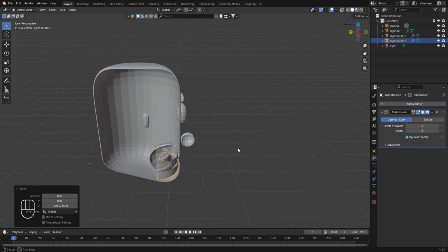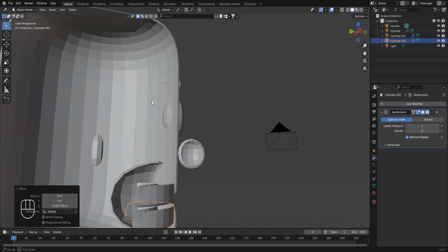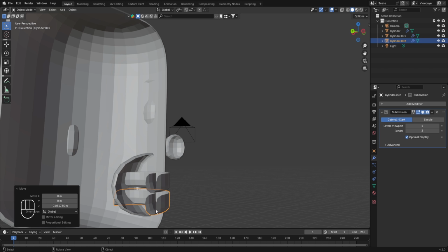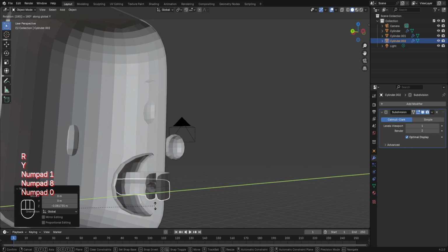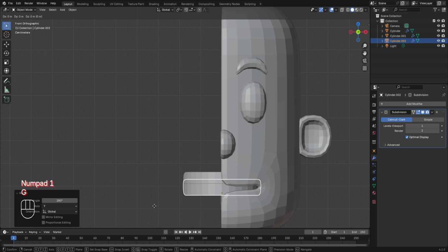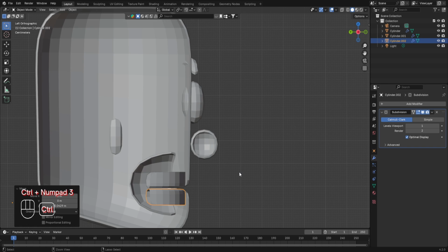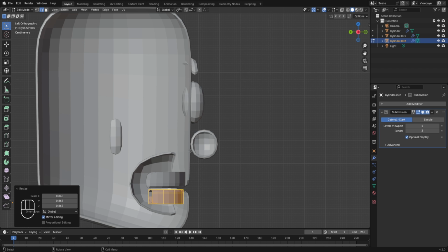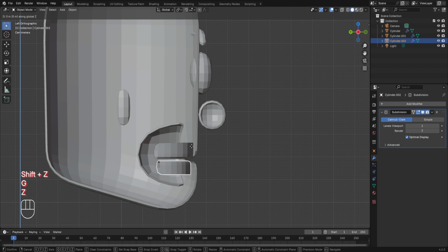But if I change the angle, then you can see here that for the lower teeth also, we have the hollow space on the top and the filled faces on the bottom part. But to get the reverse result, we need to rotate this object in the Y-axis by 180 degrees. So press R, Y and enter 180. Let's go back to the front view and move it down in the Z-axis. Now left click to finalize. Also let's go to the side view, tab into the edit mode, and let's slightly scale it down so that the upper teeth have a slightly higher size as compared to the lower teeth.